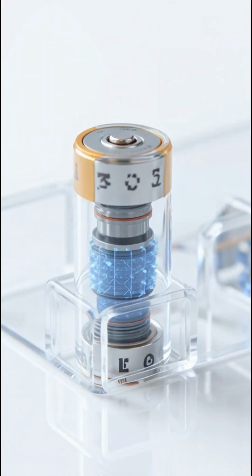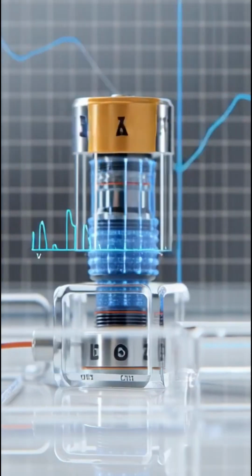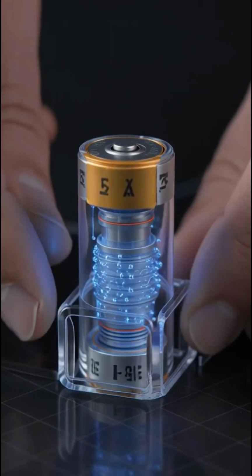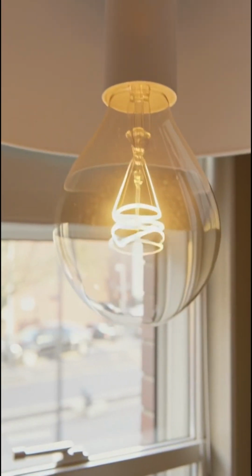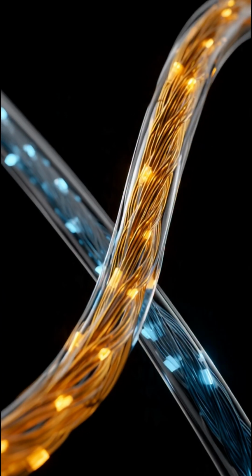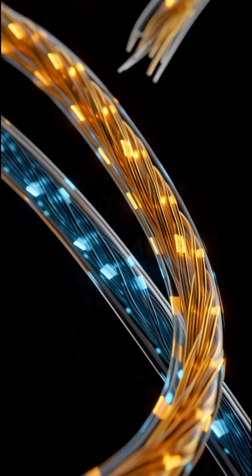Bringing it all together. Although AC and DC literally refer to current, we use those terms to describe both voltage and current behavior. DC voltage remains constant over time. DC current flows in a single direction. AC voltage continuously changes magnitude and polarity. AC current alternates direction as the voltage switches polarity. So while DC delivers a steady push in one direction, AC keeps switching back and forth, rapidly and repeatedly.